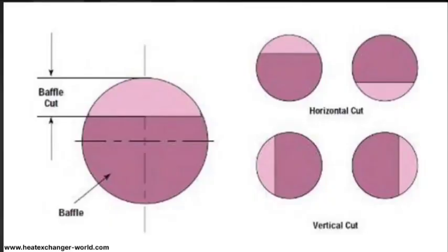But we received our payment 6 months ago. Anybody want to answer? What was the question? Baffle cut means what? There is no baffle cut, and the baffle is full support type. It's a flat plate they added. Due to this, shell side fluid cannot move from one compartment to another compartment.